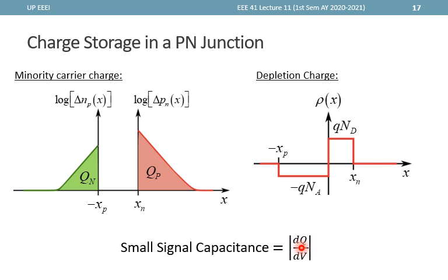So there are two sources of charges in our PN junction. First is the minority carrier charge. When we change the bias of our diode, we are actually storing some incremental charge within the quasi-neutral regions. However, this charge is quasi-stored: it looks like we're maintaining this charge, but this charge is actually recombined and just replenished every now and then by the current through the device.